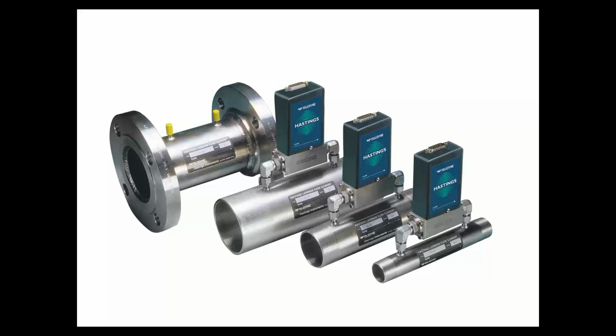As flow travels through the pipe, some of the flow passes up through the thermal mass flow meter that's mounted there via elbow fittings, and in turn, a fraction moves through the heated capillary flow sensor. So we can reach some very large flows. In fact, the meter shown on the far left there features an 8-inch flange, and that meter can measure flow up to 15,000 standard liters per minute of air. And then our LFEs, they can be shipped with pipe thread terminations, smooth, where they can be welded into other pipes, or flanges where they can be bolted into systems.